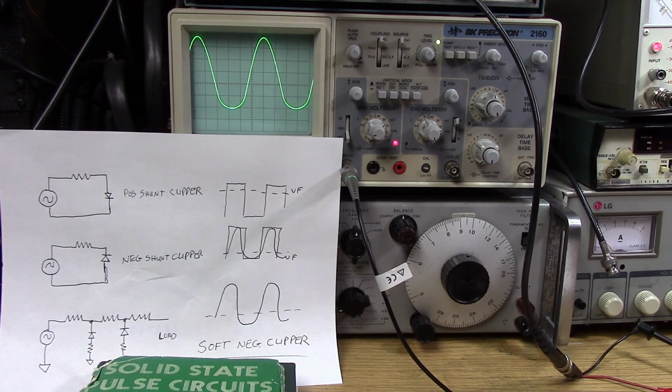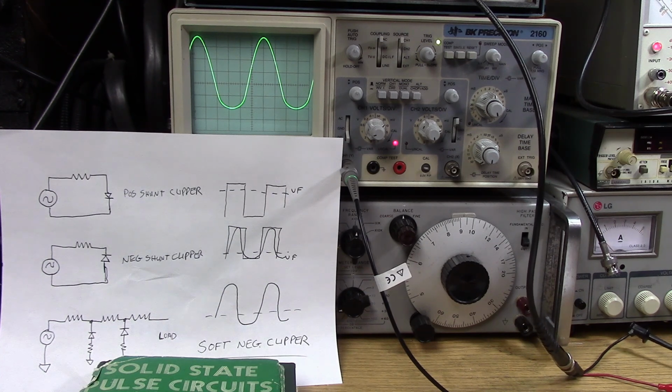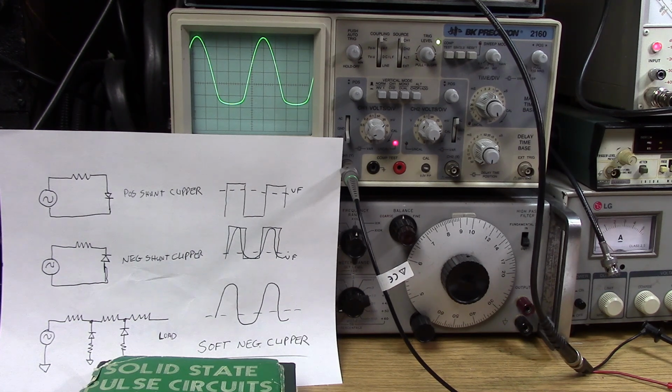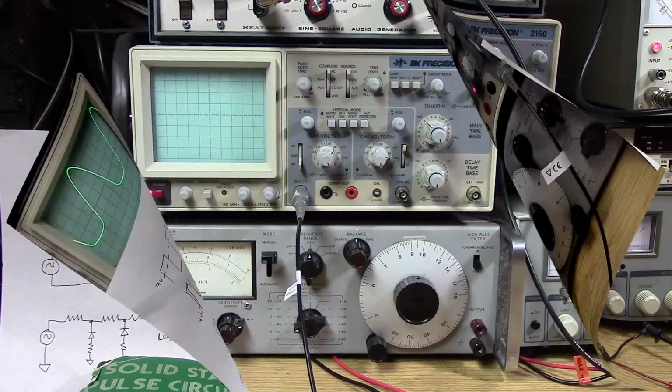This is going to allow the diode to turn on a little softer, and you can see how that's rounded the bottom. Okay, so now we've got a second section of rounding, and we end up with a little sharper clipping, but again the bottom is rounded out, and that's what I'm going to go with, a 2-section softened clipper.